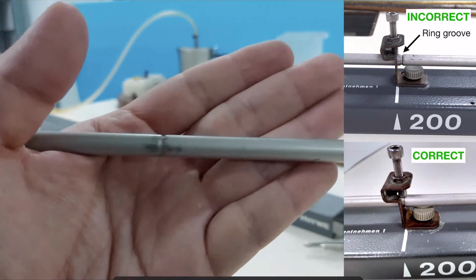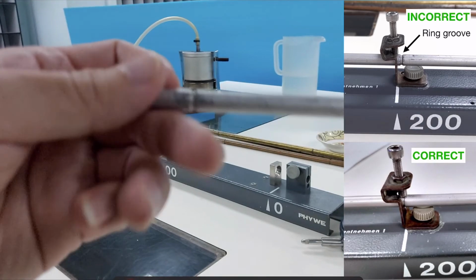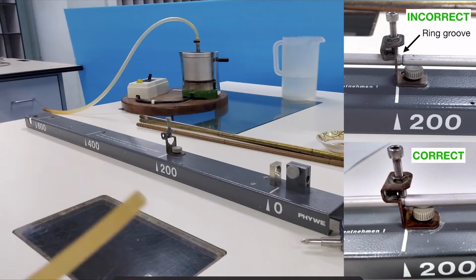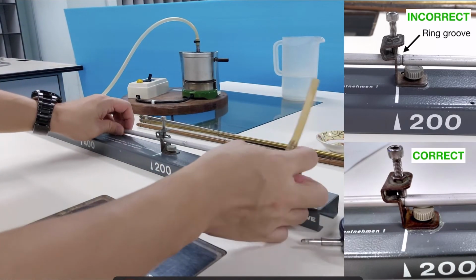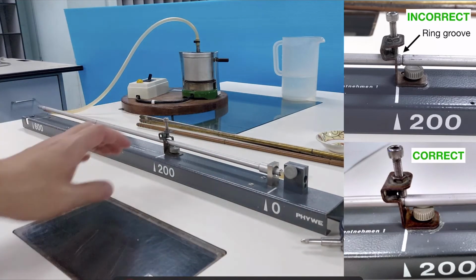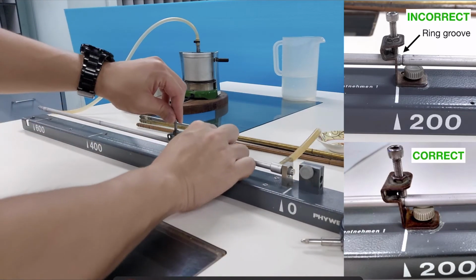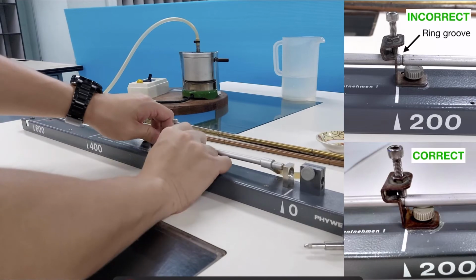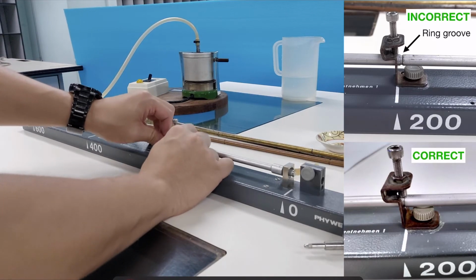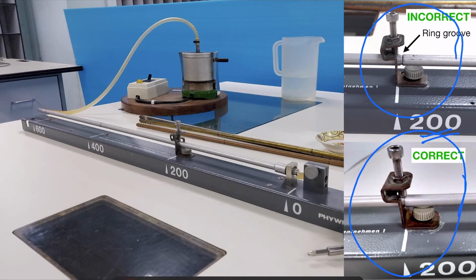Okay, this is the video, and what I'm showing is the ring groove on the metal tube, and this is the aluminum tube. Then you insert the aluminum tube into the gliding fitting attached to the clamp like this one, and make sure that the ring groove is placed exactly at the clamp as shown here. It should be like this, not like this.